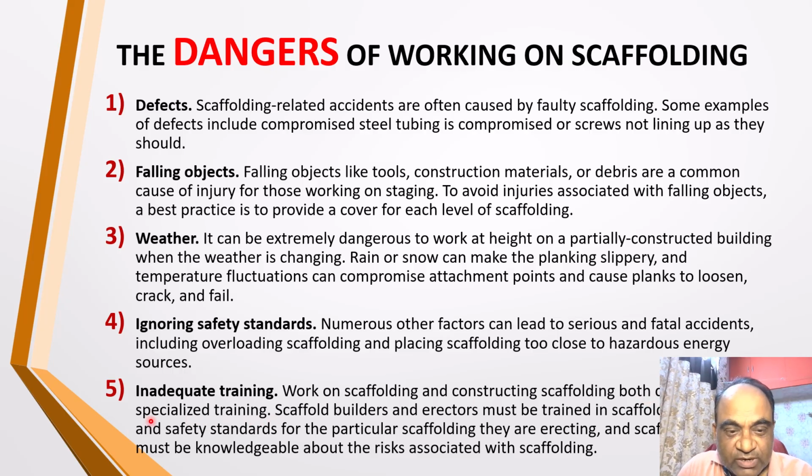They have to be properly trained before they go to work. Scaffold builders and erectors must be trained in scaffolding construction and safety standards for the particular scaffolding they are erecting, and scaffold workers must be knowledgeable about the risks associated with the scaffolding. This is very important to avoid any kind of danger.